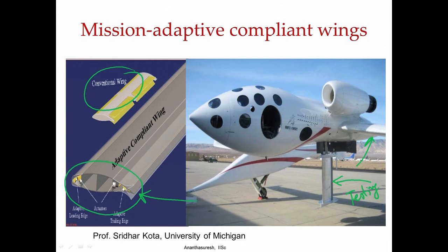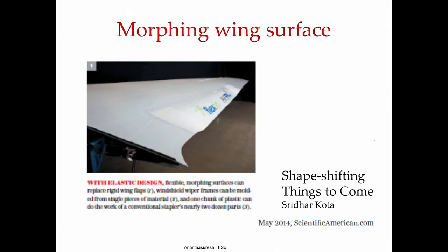So, there are really interesting applications, shape morphing, and many other things in aerospace components. Here is a version of that. There is a company called Flexsys. You can look at that website to see how this compliant wing changes its airfoil shape as per the need. When you give an actuation inside, wings do not have that much room, especially towards the tip, but that is where you need the deformation, and that can be done with compliant wings that are inside this.